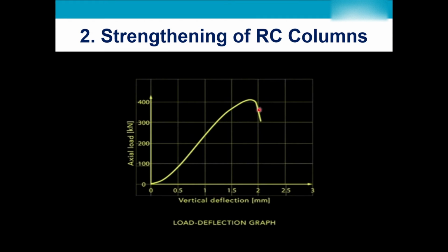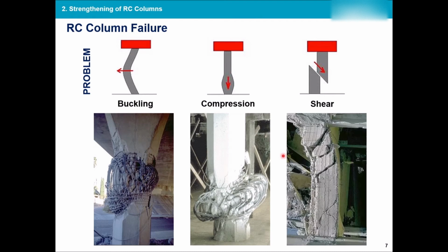And this is a simple stress versus strain graph, which we can convert to axial load because stress is force over area, as well as the strain, which is the vertical deflection, or in a normal situation, strain is change of length over initial length. You can see the graph can be plotted and we can figure out what is the capacity of our section. Now, out of that demonstration, the most important bit was to understand how a column reacts under different loading.